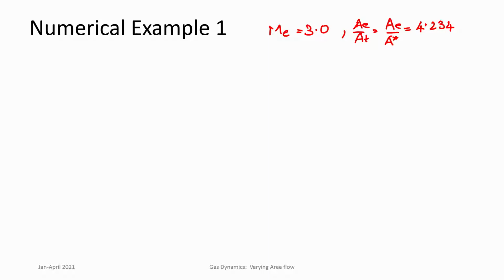Just to get numbers in place so that you have an idea what these numbers are, let us assume that P naught is about 10 bar. We could discuss it in non-dimensional numbers also. P by P naught is enough, but this gives a feel for numbers. So the first critical point occurs when the Mach number at the throat is 1 and at the exit the flow is still subsonic. There are no shocks inside, so the flow is isentropic.